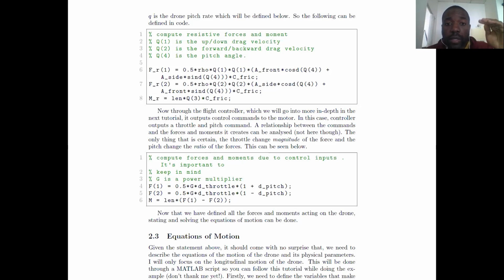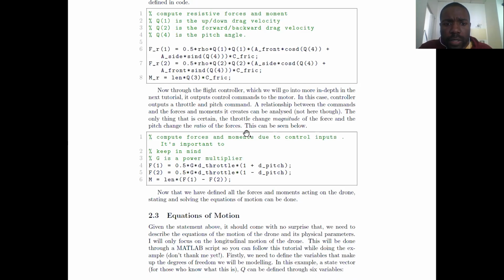It means you're able to change how much of that magnitude is partitioned between the two motors. So if I turn the knob, I can change the length of it, and that changes the moment about the center of gravity, and that creates this motion. If it was just equal, it will obviously just rise in this fashion. If it's different, it will obviously rotate. And that's the commands you send via the flight controller.